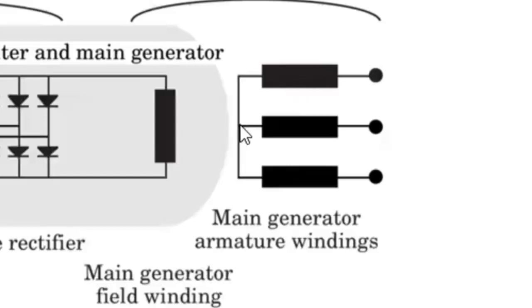and that is, after selecting continuity, you place one of your probes at the start point, okay, and then you probe the terminal of line 1, that will give you the resistance reading of the U phase. Terminal of line 2 will give you the resistance reading of the V phase, and the terminal of line 3 will give you the resistance reading of the W phase, okay?